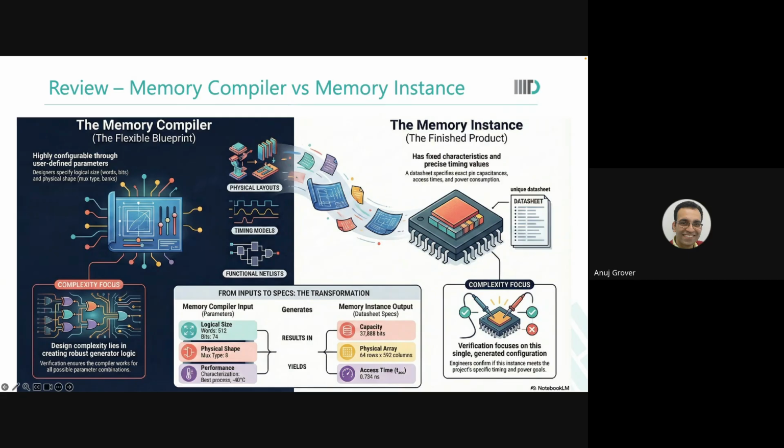And not just that. Inside a .lib, you have seen there is a rectangle, a matrix that is created. Input slope 1, input slope 2, and then what are the timings? Have you seen those matrices? A similar thing would exist for load. So if the load increases or decreases, the cells you created in DVD are characterized over a range of loads, over a range of input slopes for every timing. Every timing arc is characterized over a very wide range.